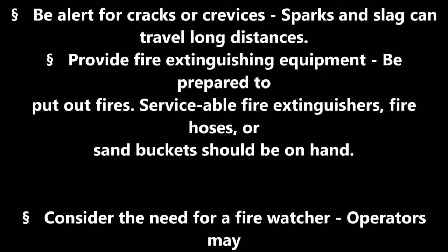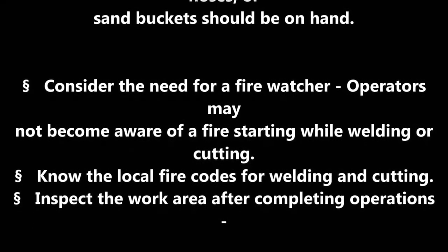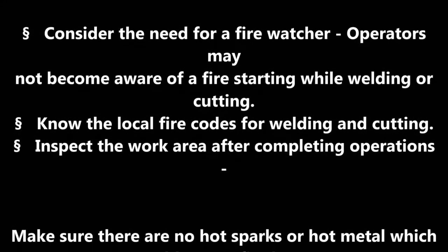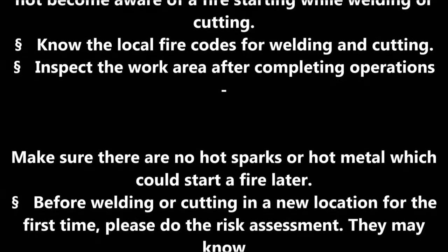Provide fire extinguishing equipment. Be prepared to put out fires. Serviceable fire extinguishers, fire hoses, or sand buckets should be on hand. Consider the need for a fire watcher. Operators may not become aware of a fire starting while welding or cutting. Know the local fire codes for welding and cutting.